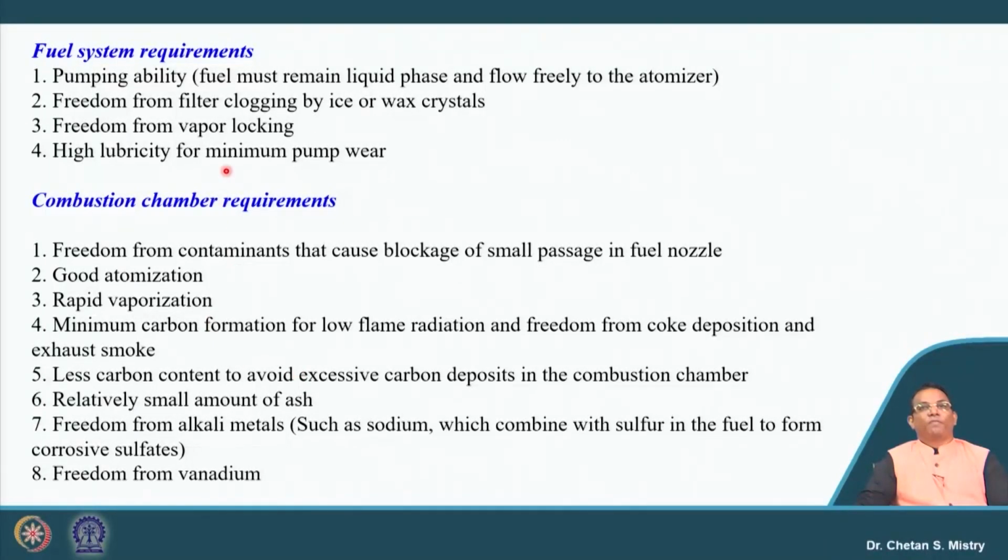It should be free from filter clogging by ice or wax crystals. It should be free from vapor locking, and have high lubricity for minimum pumping wear. These are all the properties required by the fuel system.